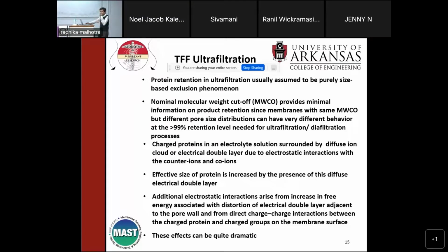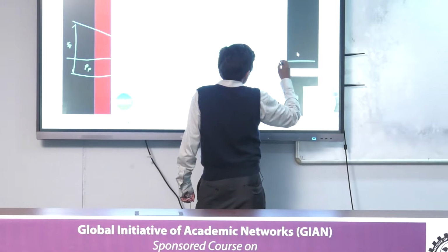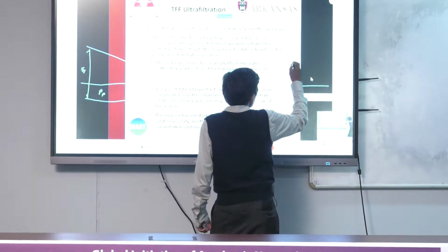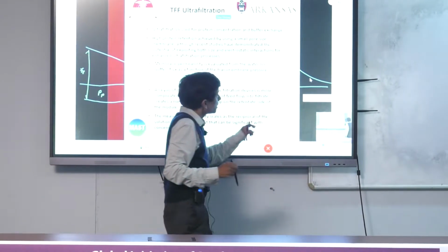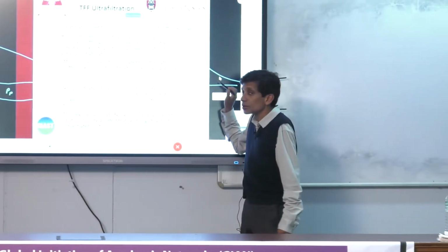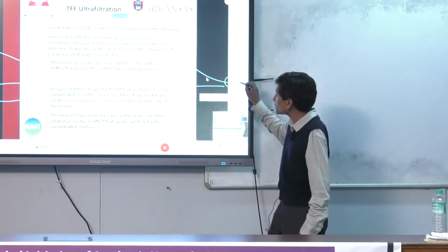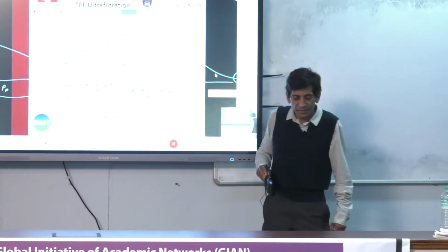So I think we talked about this earlier, that we don't know what the minimum pore size or the maximum pore size is, but we have different pore size distributions. And typically, these pore size distributions look something like this. I'm exaggerating here, they look something like that. So this might be the modal size, and often it's modeled like this as a log normal distribution where you have a very long tail here, and here, of course, it can't go beyond 0, right?